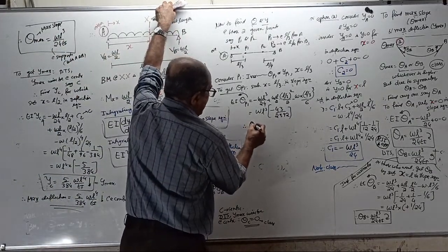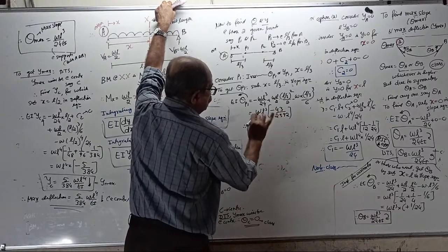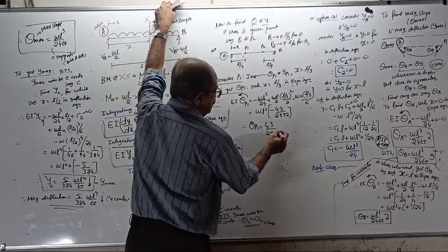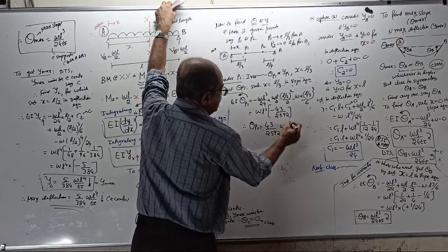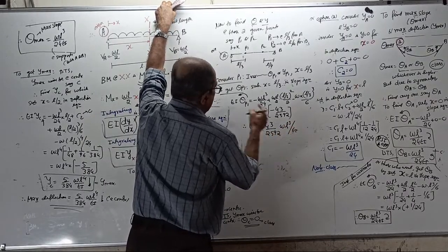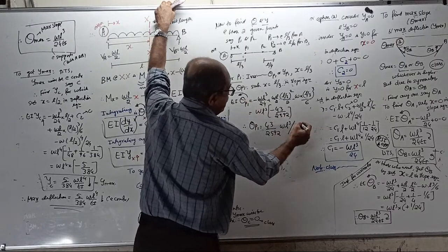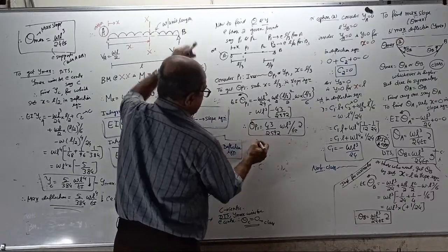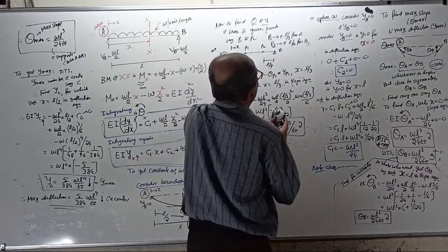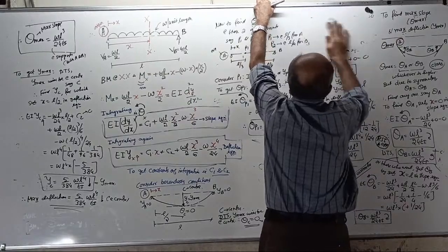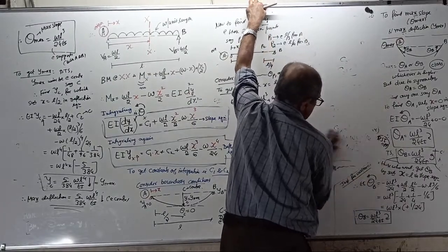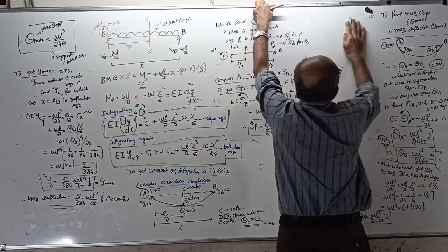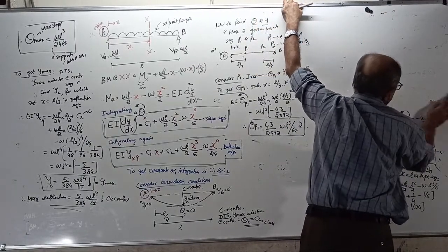Therefore, slope at the point P1 equals, no minus sign, 43 by 2592 times WL cube by EI, anti-clockwise positive, negative came, so that much clockwise. Over. Theta P1 is over. Next, I'll write here now. After theta P1, use the space here to save the time. Little later I will reduce the board size, because the only purpose is to see that everything is visible for you.